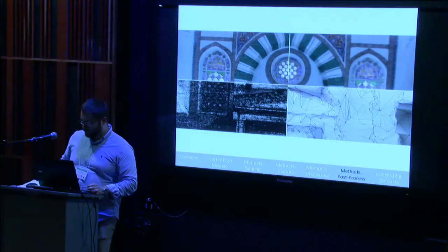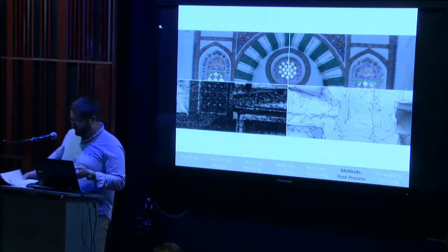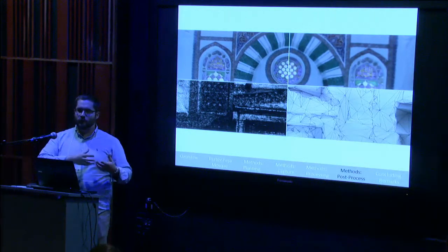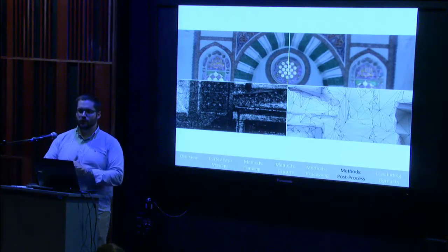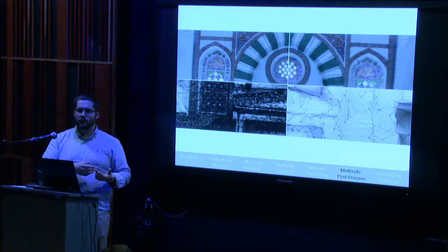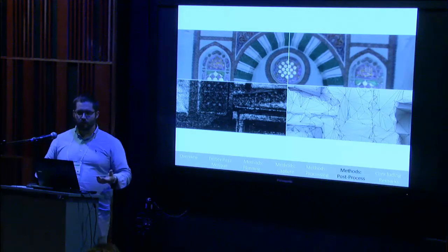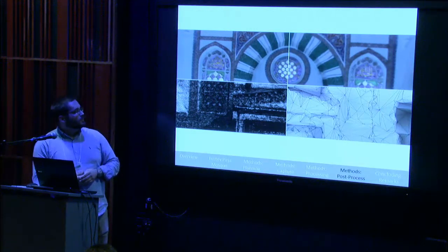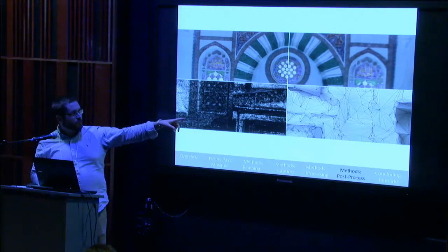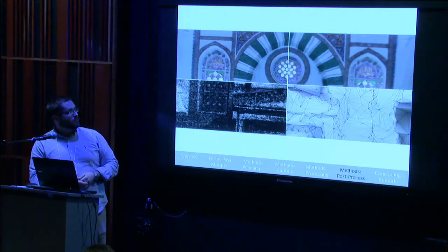After processing the mosque and having the entire model, we decimated the mesh, which is essentially reducing it to try and preserve the overall shape, the overall form, and any substantial changes, but at the same time eliminate any duplicate meshes or lots of detail in places where it's completely unnecessary. You can see this was our original mesh, which is very, very dense, and that was the final mesh that it was decimated down to, and then there are the associated texture maps above.